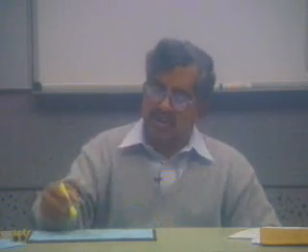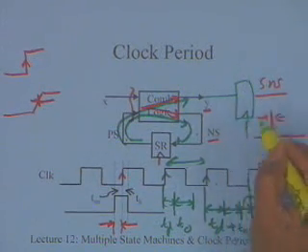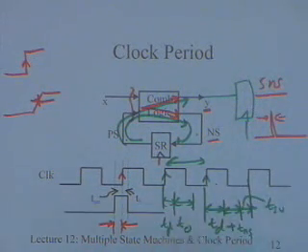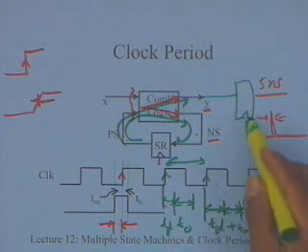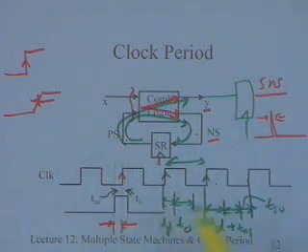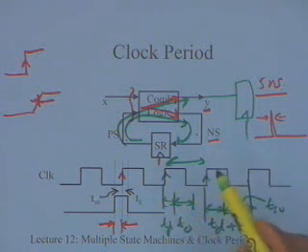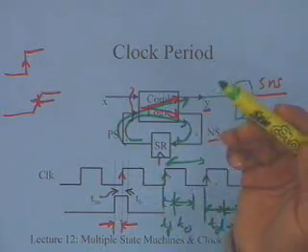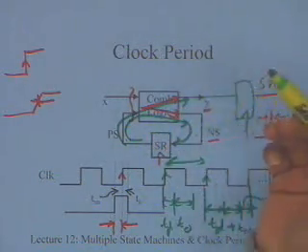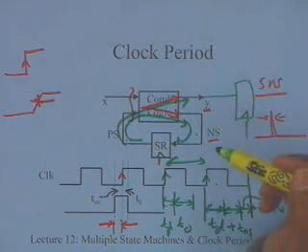And most of the time what happens is that you take the output and you generally latch it with another register. There is a very common usage that happens, and if you try to do that, then again this problem will be there, that each time you are latching the output you do not know whether it corresponds to this particular output or the next. So some outputs may just be missed because the last output has come and the next output has also immediately come before this next clock.